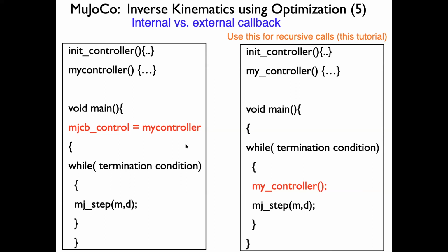That is, my controller will call dsim, dsim will call my controller, and it'll just loop through infinite time and get you nowhere. To avoid that, I actually make the callback external. So when I define dsim in my controller this way, it can be executed first, and then the command is passed to mj_step. So to avoid the recursion, I had to do this.